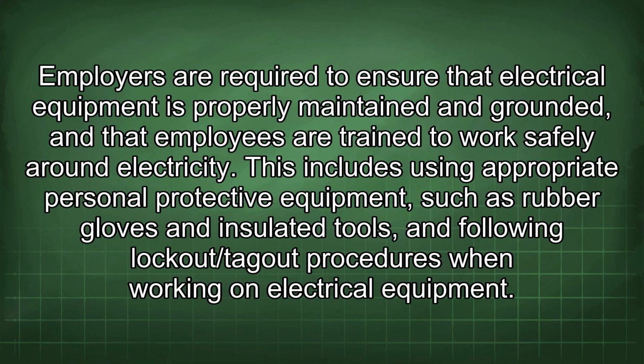Employers are required to ensure that electrical equipment is properly maintained and grounded, and that employees are trained to work safely around electricity. This includes using appropriate personal protective equipment, such as rubber gloves and insulated tools, and following lockout/tagout procedures when working on electrical equipment.